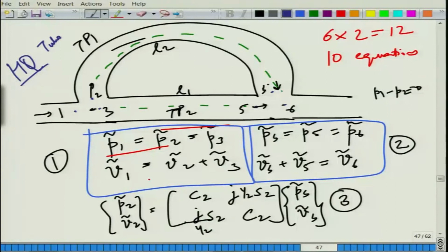What we are going to do in the next lecture, that is lecture 2 of week 10, is derive the transmission loss for such a tube, which is called an HQ tube, Herschel-Quincke tube. It has a minimum of 2 tubes, and you can have multiple such tubes. Because of the path difference, we have constructive or destructive interference between waves, leading to some non-zero transmission loss. Note that we have a uniform cross section across this thing. In spite of having uniform cross section, you have non-zero transmission loss in general because of this destructive interference at certain frequencies.